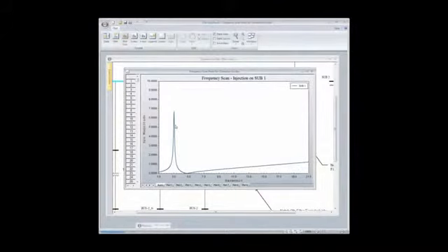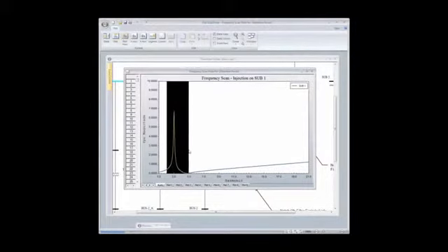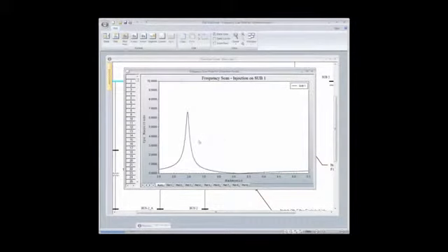Every time you have a filter put on a bus of some form, you're going to be pinching it down to a filter point, and it's going to manifest or react to that and create a first parallel resonant point below the filter. So for this fifth harmonic filter, we have a first parallel resonant point, which in my opinion is not really in a very good place. I would recommend that you position this away from the third harmonic.